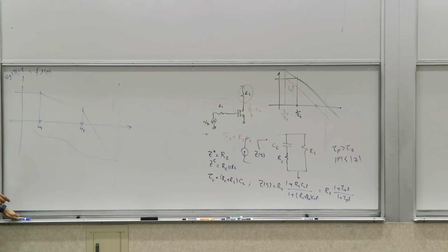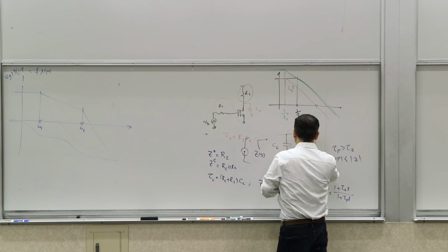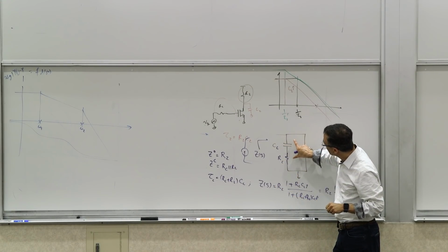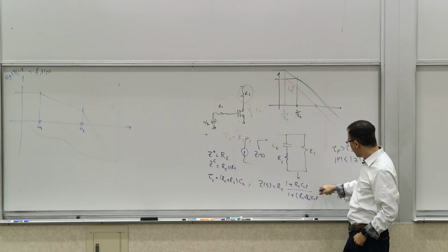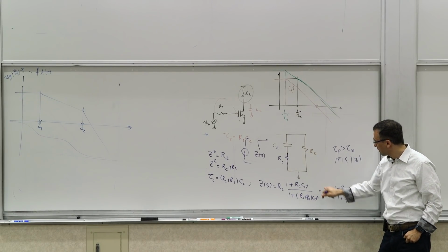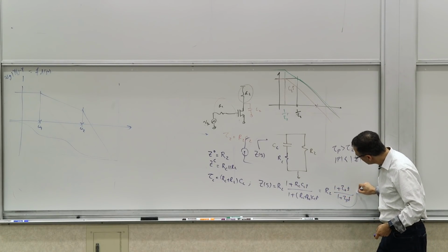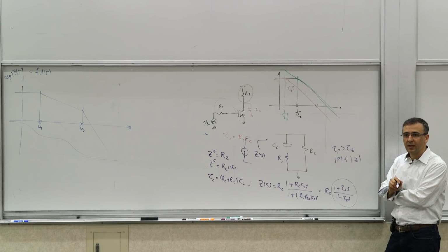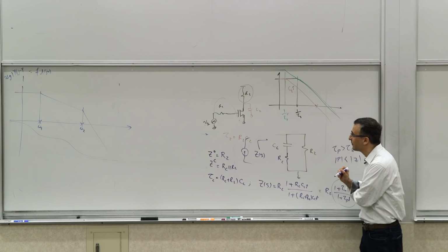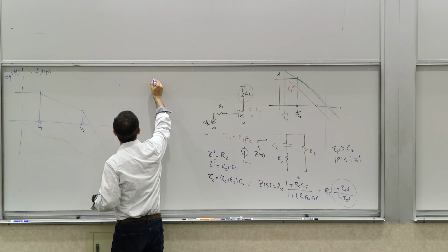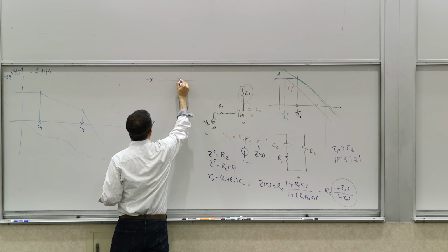So now this new load, if I replace my load, some resistor that's acting as a load, if I introduce this branch in parallel, I can take that load. At low frequency, I still have that load, so my low frequency gain and everything doesn't change. But I introduce this pair of poles and zeros, and both of them are a left half plane pole and a left half plane zero. So I have the ability to put a pole-zero pair. The only constraint is that my pole will happen before my zero.